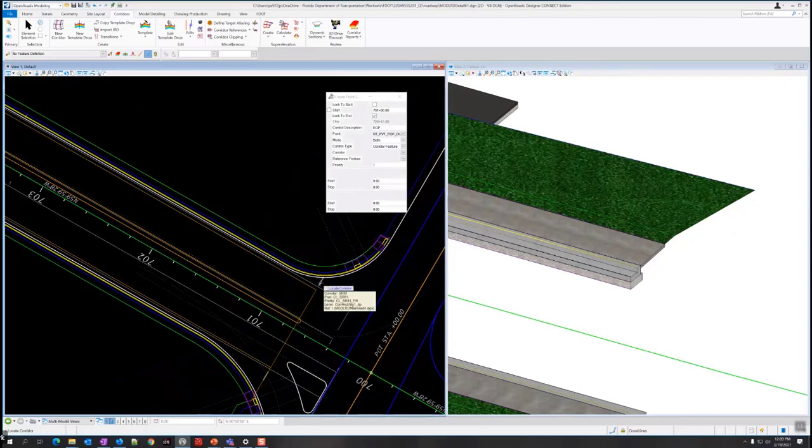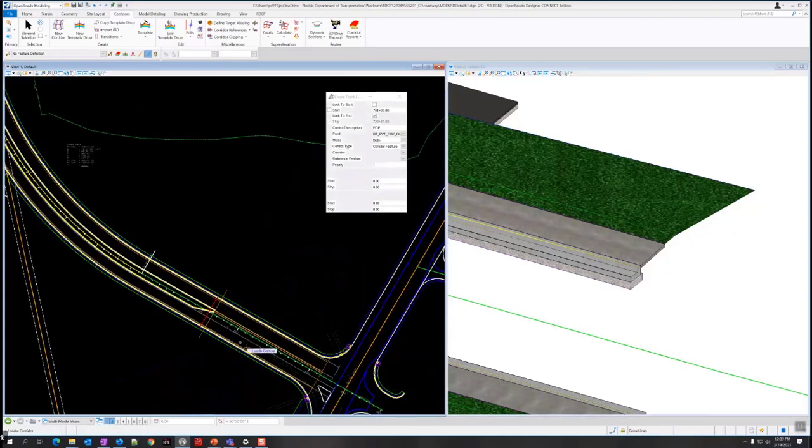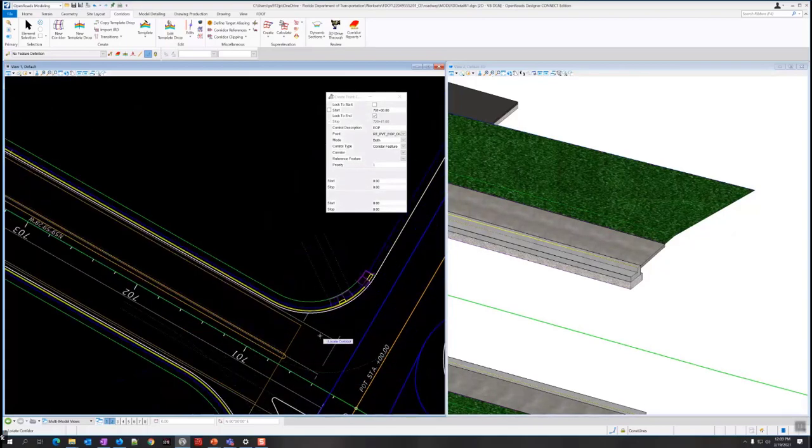If you hover over it, you get the little pop-up. That may help because it says corridor SR61. This is the corridor handle, and it also points out that it's from a reference. It's from the MODLRD mainline 61. So that's the one I want. If you come over here, you're going to have handles for that one, and handles for this other corridor, so it may be easy to get the wrong one. So we'll select this right here.